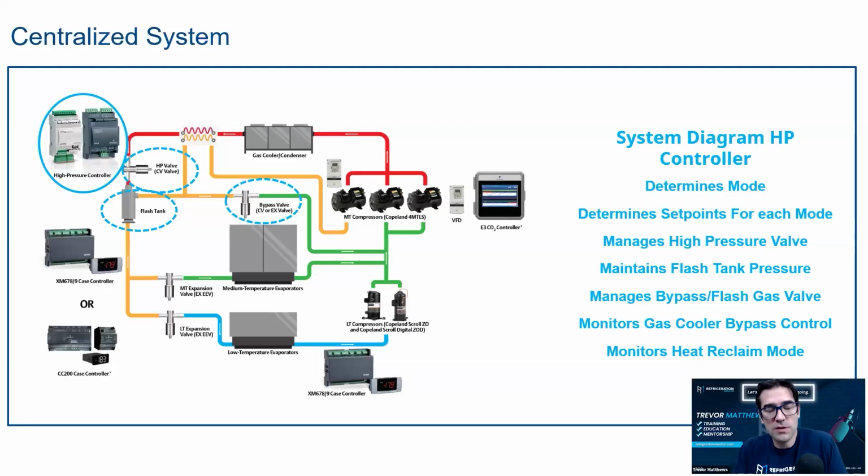What the graph you showed there is so important as a technician. So anybody listening on the podcast, it's the trend graphs. You've got to go in and look at those different trend graphs. As you see with Andre's slide, he had the percentage of the valve open. He had the fans on and off and the percentage of their speeds. You have to be looking at that, as well as the temperature, the drop leg center, and you've got to plot that stuff. This is how you troubleshoot remotely or at a site. You've got to look at what happened and what you need to do to remedy that.